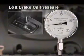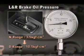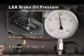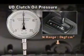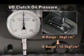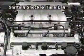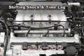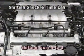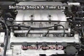The oil pressure of low and reverse brake increases to 10.5 kilogram force per centimeter squared from 3.5 kilogram force per centimeter squared when D range is selected from N range. On the other hand, oil pressure of underdrive clutch increases from 0 to 10.5 kilogram force per centimeter squared. Therefore, check the related flow path and parts of underdrive clutch of oil pressure equipment first, if shifting shock or time lag occurs when shifting from N to D.